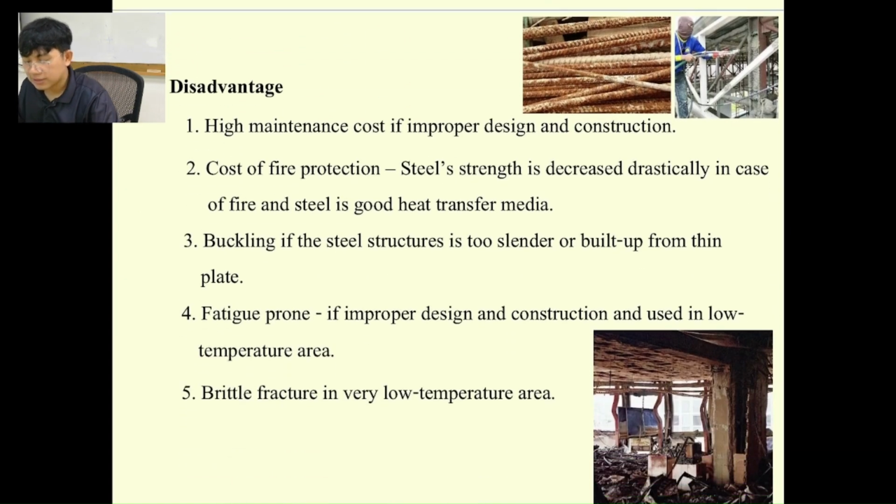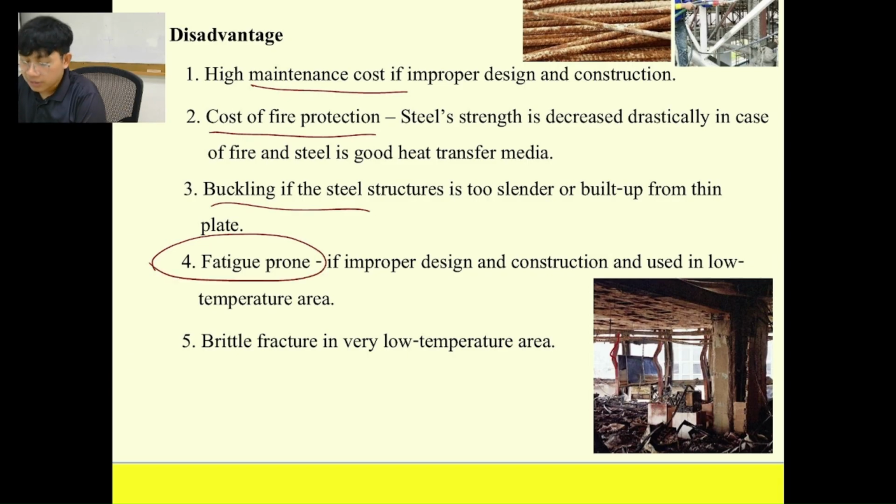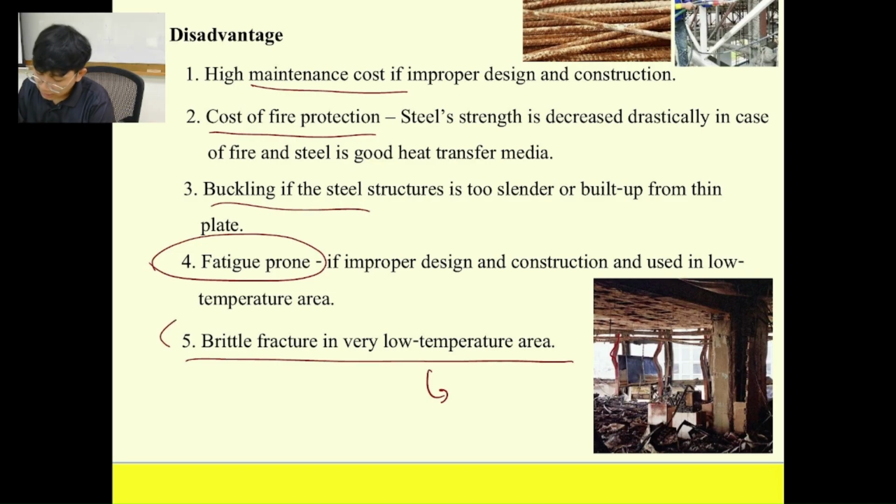Okay, and we also have several disadvantages. The maintenance cost may be higher, and then we have the cost of fire protection. Also buckling of the steel, if something does not happen according to what we designed, it's going to buckle. And then fatigue can happen if you design it to be higher than the endurance limit. And lastly, brittle fracture may occur, though we may not experience this here because it may be too hard.